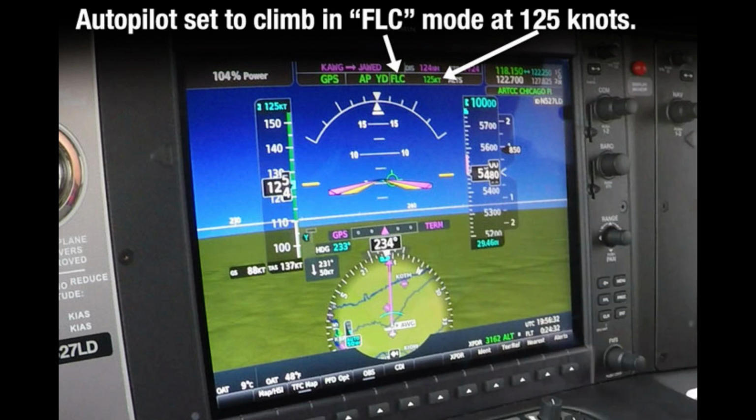Distinguishing between armed and engaged adds complexity to the process of maintaining mode awareness. In addition to autopilot functions that are engaged by the pilot, some autopilot functions engage and disengage automatically. Automatic mode changes add to the challenge of keeping track of which autopilot functions are currently engaged and which functions are set to become engaged.